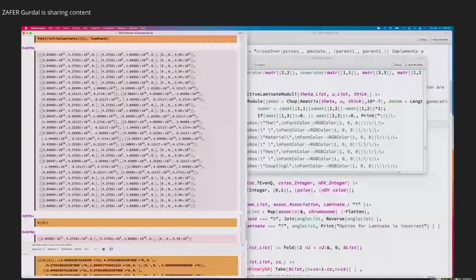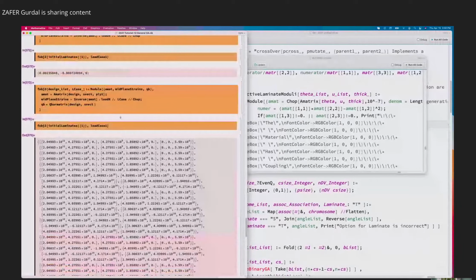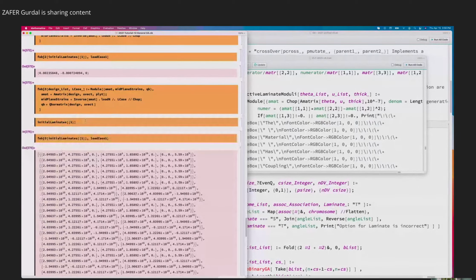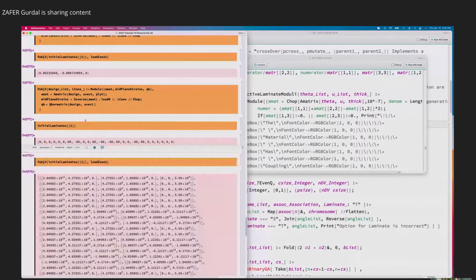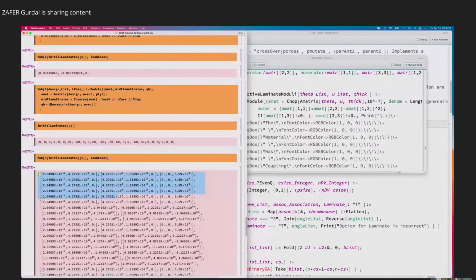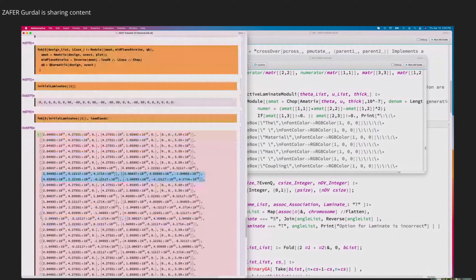Second one. What was the design that I'm sending in? This is what I'm sending in. Design that I'm sending in has 1, 2, 3, 4, 5, 6 layers of zeros. So Q bar of zeros are these 6. And the second design, initial limit 60 and minus 60, has these Q bar matrices. So everything is as expected.